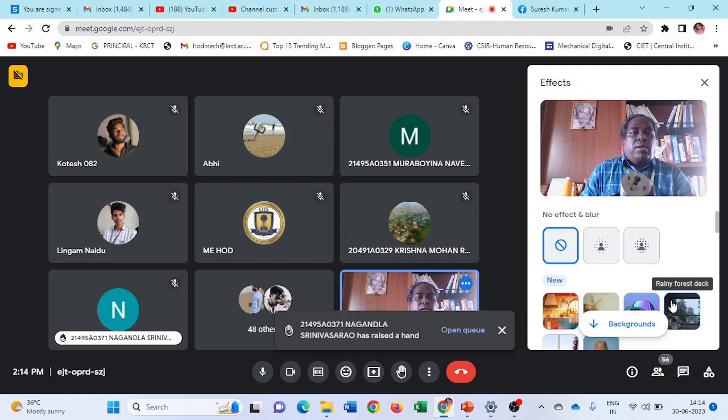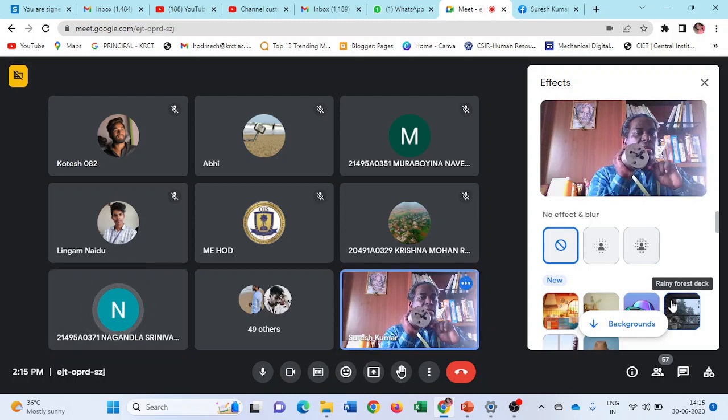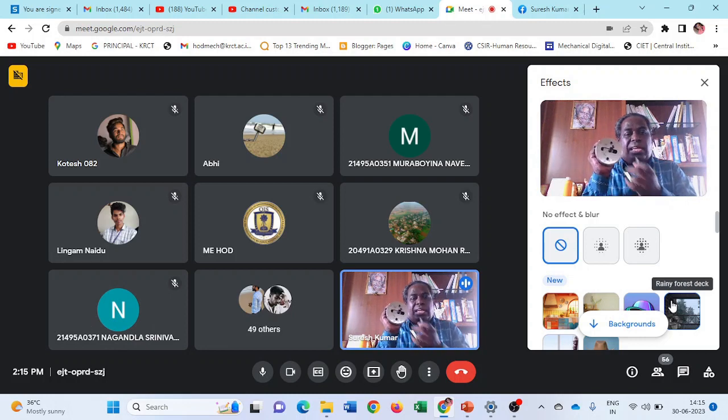To avoid this, in our campus, myself and my students invented this kind of project, which was one of the final year projects of a mechanical engineering student. Here he introduces the same shank part, but he introduced one hub part. In that hub part, there is a transient movement boring bar available. With the aid of an Allen key, he may adjust the transient boring bar with this assembly. From this, I can get the exact dimension.